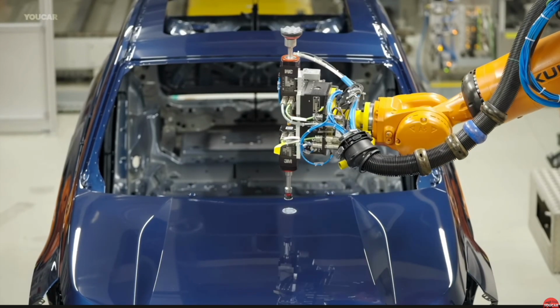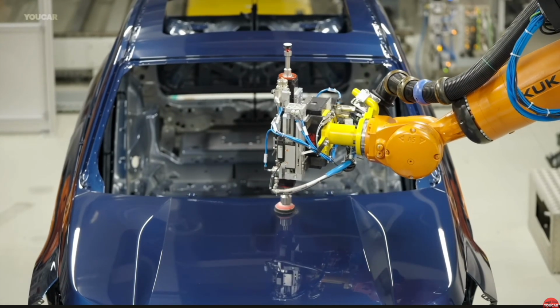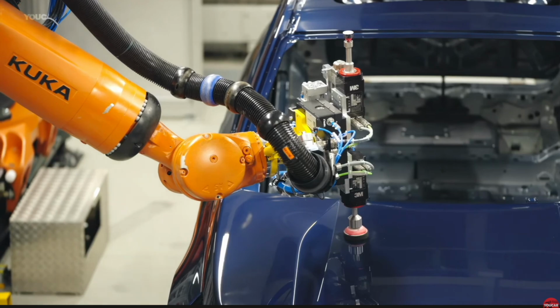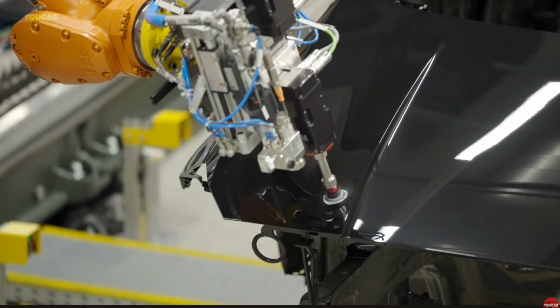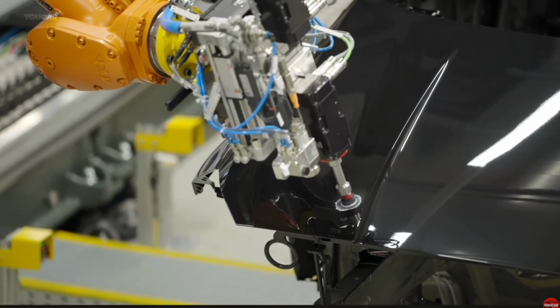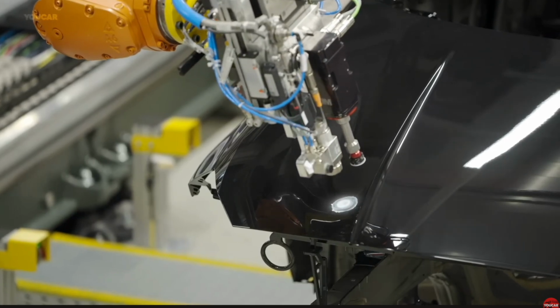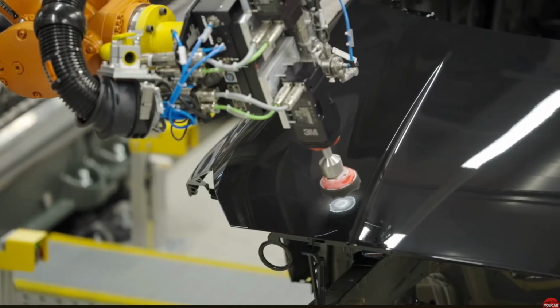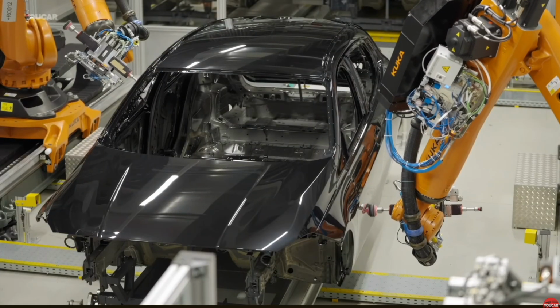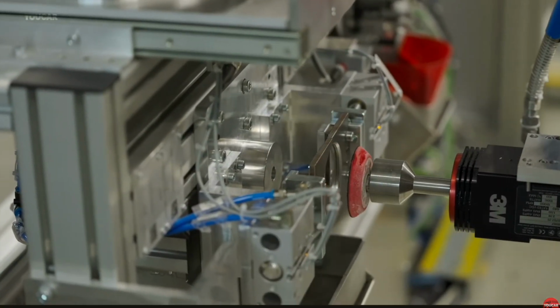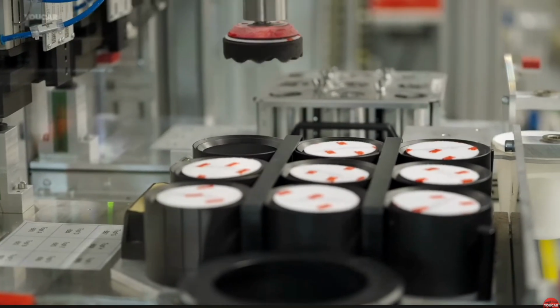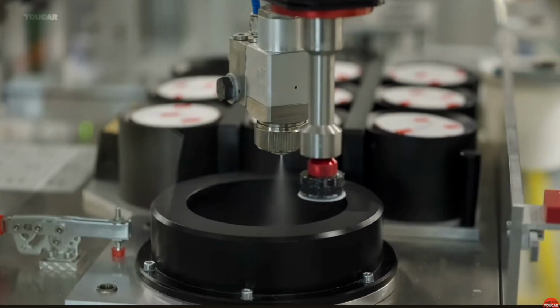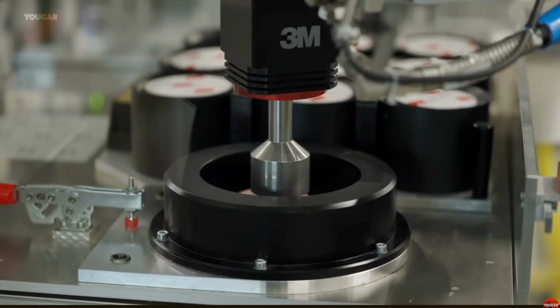Here is an example of a BMW automated paint shop. After a vehicle has finished its painting process, it is scanned for any remaining punctures or defects. Then several robotic arms are equipped with rotating tools that apply compound to smooth out the defects. The final product is a clean finish and an exterior with minimal defects. Buffing a surface can achieve a glossy appearance and a smooth surface finish.